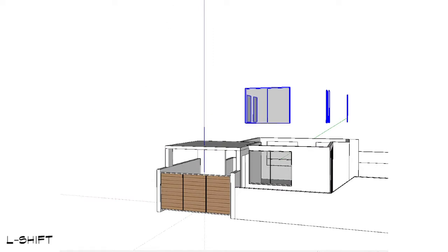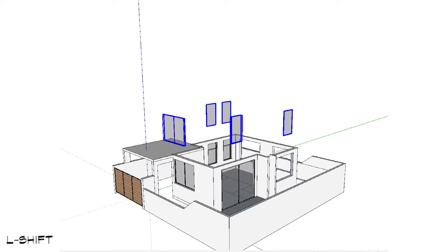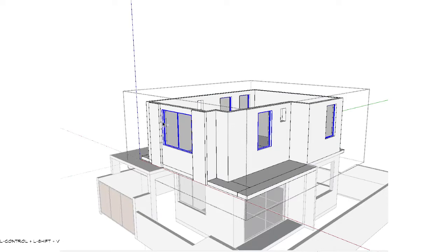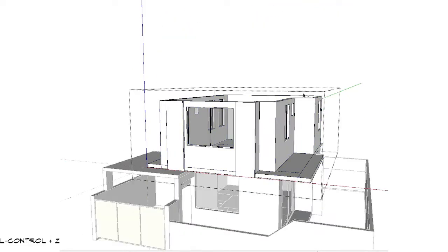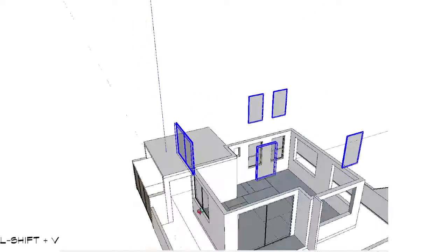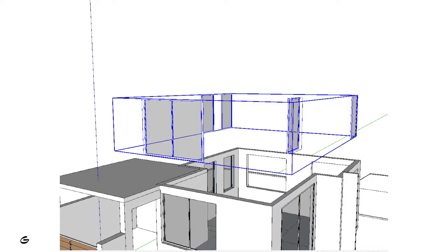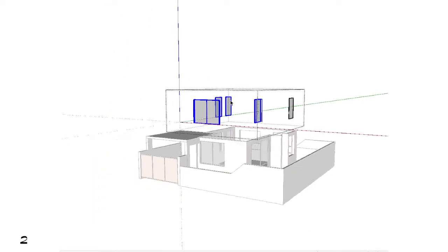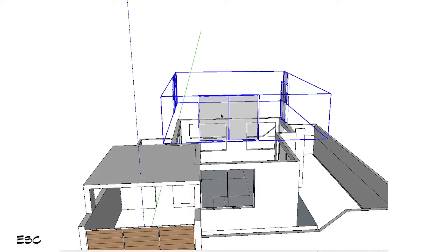So for our openings, we put them in A openings. Now what I could do is cut and paste them inside the second group, or the second floor. Or, let's say for example they were already outside, you can just group them and press number 2, since they are components that are already in A openings. And in this case, that's what I will do, just because.